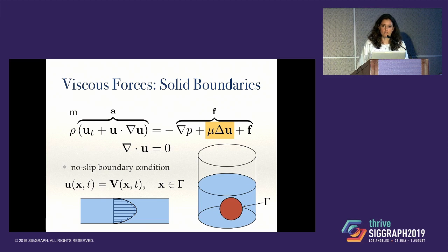Another thing that makes fluid simulation kind of challenging is getting boundary conditions right. You'll find often boundary conditions are some of the trickier parts of simulation, along with collisions and things like that. For a fluid, a very common boundary condition, especially for a viscous fluid, is the no-slip boundary condition. So the fluid wants to stick to the walls, wherever it's touching walls.